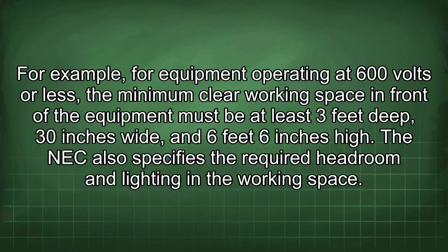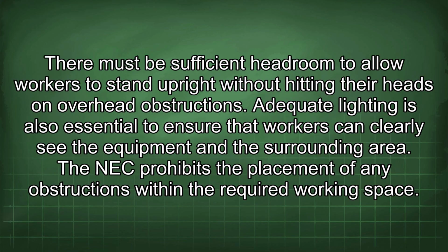The NEC also specifies the required headroom and lighting in the working space. There must be sufficient headroom to allow workers to stand upright without hitting their heads on overhead obstructions. Adequate lighting is also essential to ensure that workers can clearly see the equipment in the surrounding area.